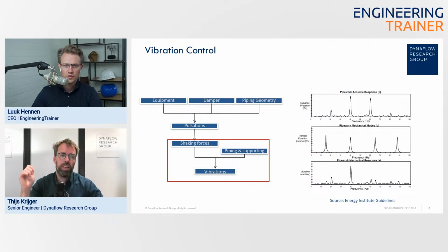One difficult thing in these kind of systems is that often the things you want to do in order to solve your vibration problems are going to cause issues for your static stress analysis. Right, because we want to make the system more rigid, place more supports, more guides, and then it doesn't leave much room for the thermal expansion.